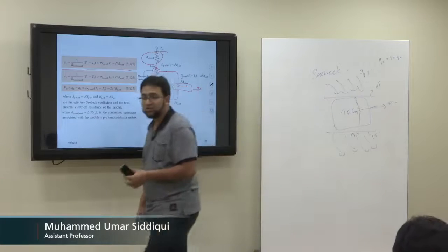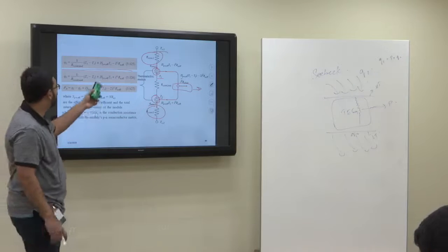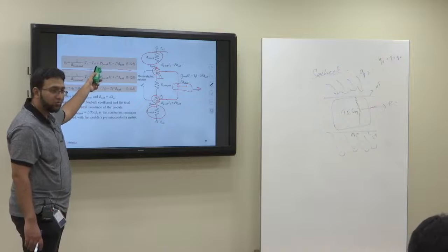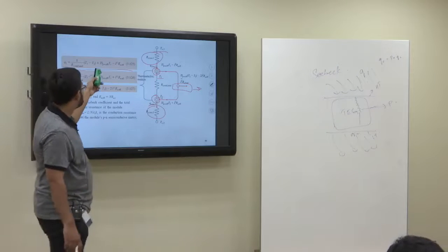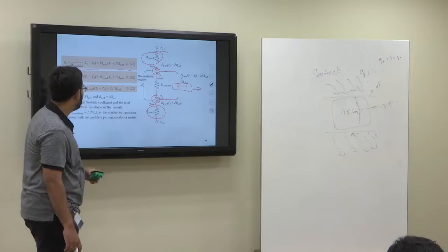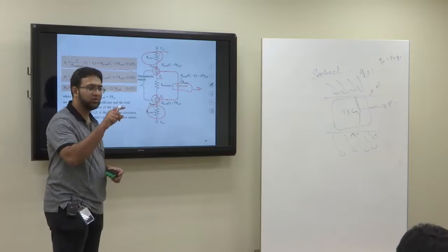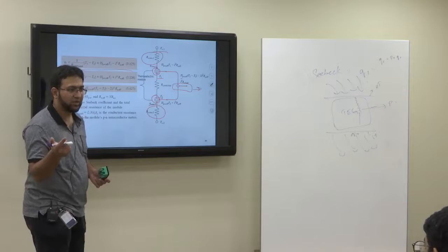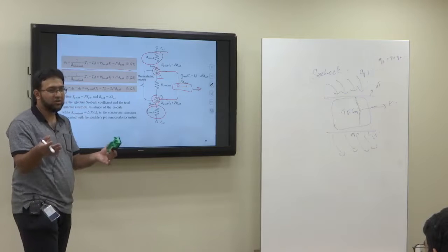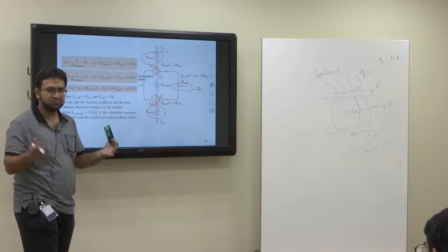Since we are using a p-n junction of semiconductors here, this will be provided to you as a constant, the Seebeck constant for that. So that is S_PN effective. It is given in the units volts per Kelvin, so how much voltage is generated per degree temperature difference.